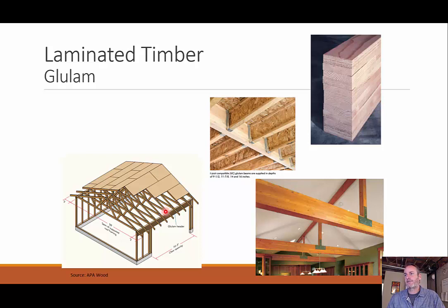So using it in residential construction, I can see that this glulam is a primary beam, and then I have these I-joists coming in. Because we already know, we learned from our last video, that the I-joists are much stronger so I can have a greater span. Well, the problem with that is you have a whole lot of load if you have a big span coming right here, so we have to support that greater load. That's why we're using this glulam, because it's even stronger since we have all these individual layers glued on top of one another. It's a massively stronger beam.